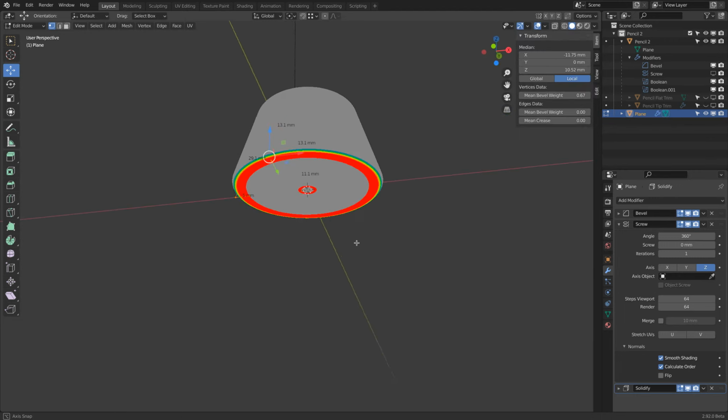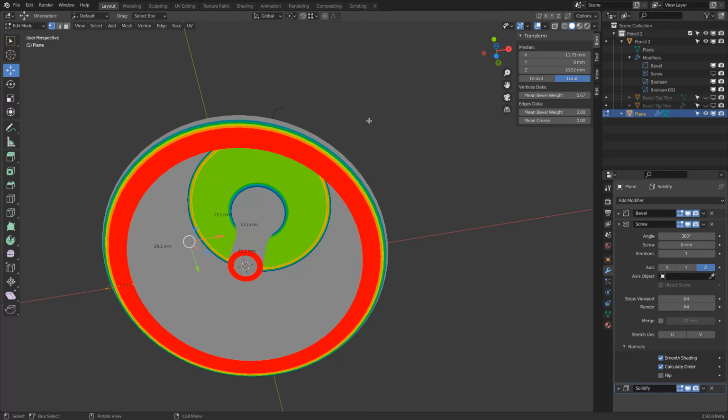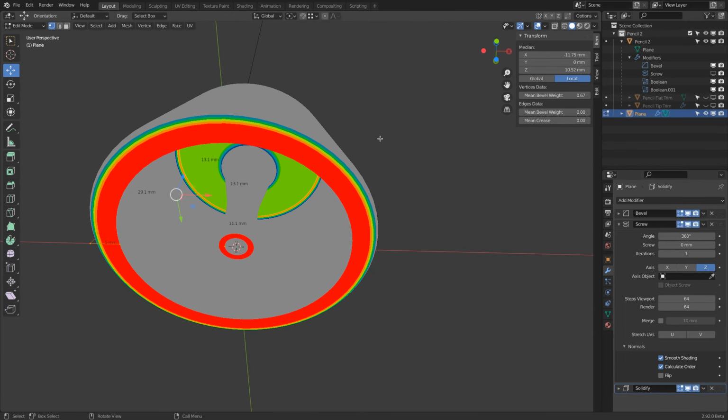We don't really see anything. If we go to the bottom, oh, look at that. There you see all the colors. So red means something is horizontal, it's like an overhang, so it would fall down. Think about the overhang like the geometry that is the horizontal bar of an H. And 45-degree, those would be the two diagonal lines of a Y.